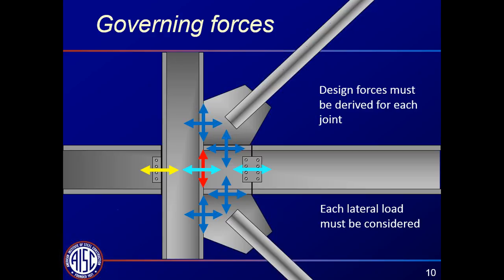In order to keep things relatively simple and consistent, I'm just looking at vertical and horizontal forces. There could be moments as well. As part of this connection, I'm showing a joint here between the beam and the larger connection assembly. That may or may not exist in your designs. If it doesn't exist, then that's not a connection you have to design.